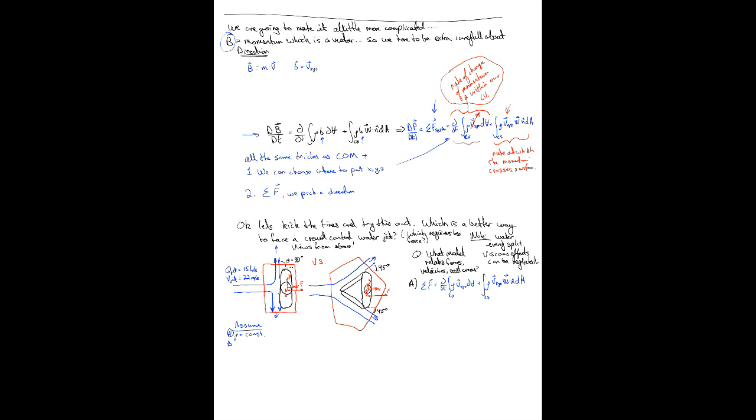Although, if you ever watch videos of this, they often wiggle the jet, if you will, so that you can adjust to limit the force on any one part of your body. So C is uniform flow. We're going to assume the jet is uniform in velocity anytime it crosses our control volume surface. Great. So we have to pick a direction now, and I'm going to choose the X direction.